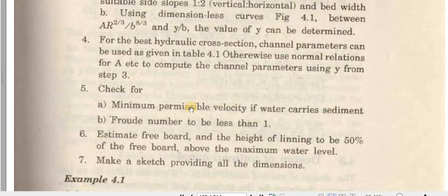If a canal is carrying some sediments, then in our design, our target should be that those sediments should remain in suspension and should be transferred from one canal to the other canal and up to the watercourse and up to the farmer field. If the velocity is less than minimum permissible velocity, then siltation will occur. So this is the case of a lined canal. So in a lined canal, maximum velocity does not affect, because the canal is totally lined, and the factor is only minimum permissible velocity.